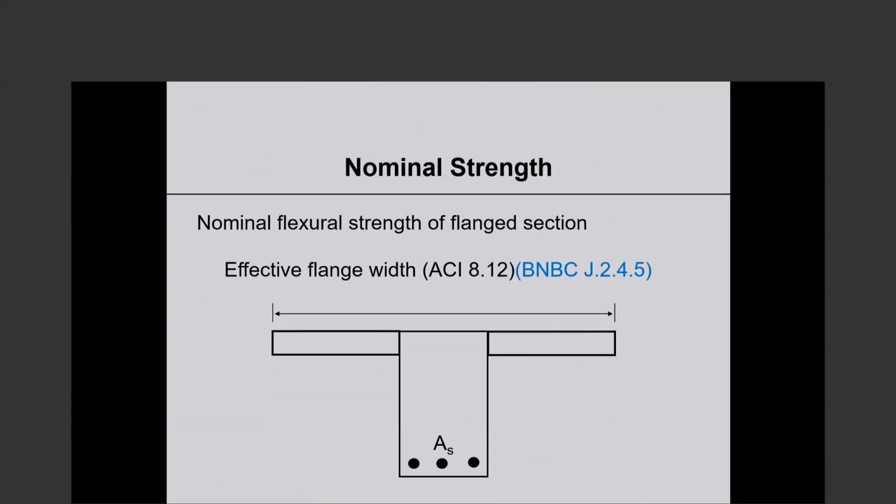Okay. So singly reinforced section, doubly reinforced section, then we go to a flanged section, a T-beam as we typically refer to it. And this is important because it is very common. We have in concrete, at least in cast-in-place concrete, monolithic construction where the slab is built integrally with the beam, and a part of the slab, as shown in this picture, acts as part of the beam.